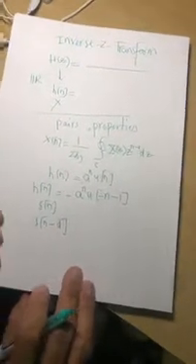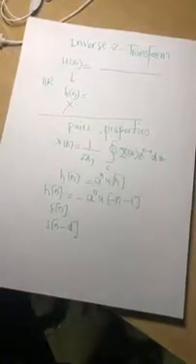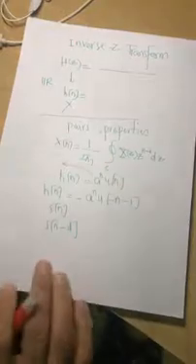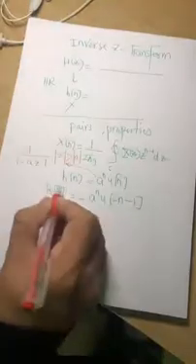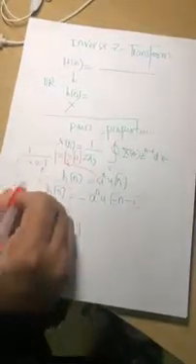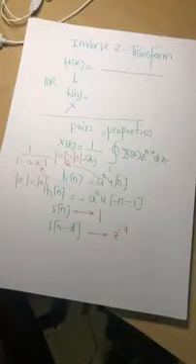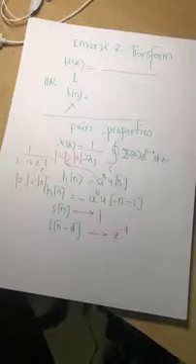And I know that for a to the n u of n, the Z transform is 1 over 1 minus a z inverse, with region of convergence magnitude of z greater than magnitude of a. For the second sequence, the Z transform is the same, but the region of convergence is magnitude of z less than magnitude of a. And for the delta sequence, the Z transform is z to the minus d. So if you know only this, you can solve almost any question in the exam which talks about finding the inverse Z transform.